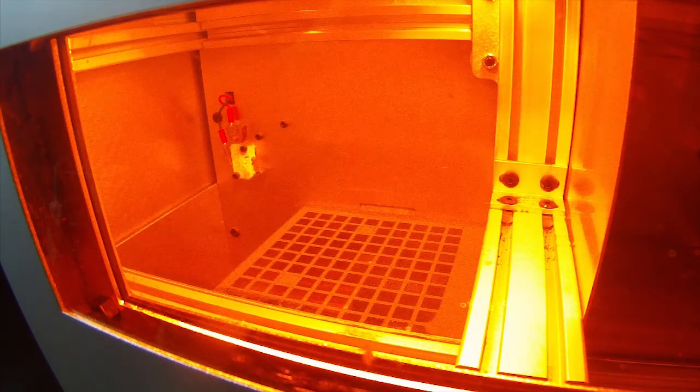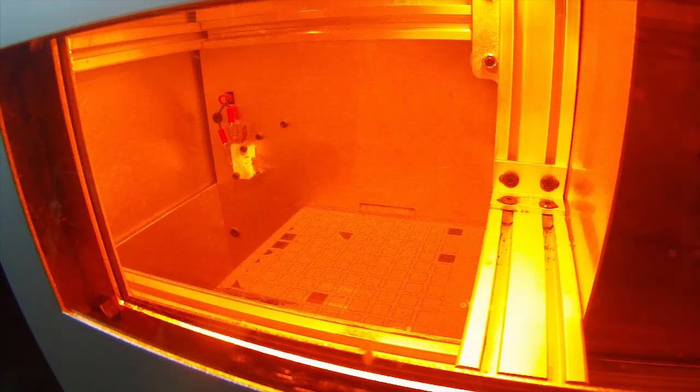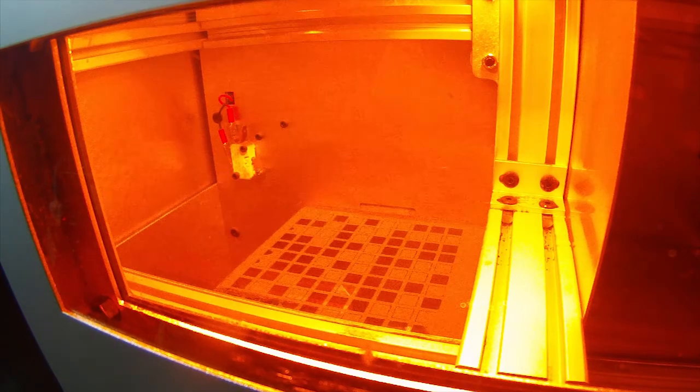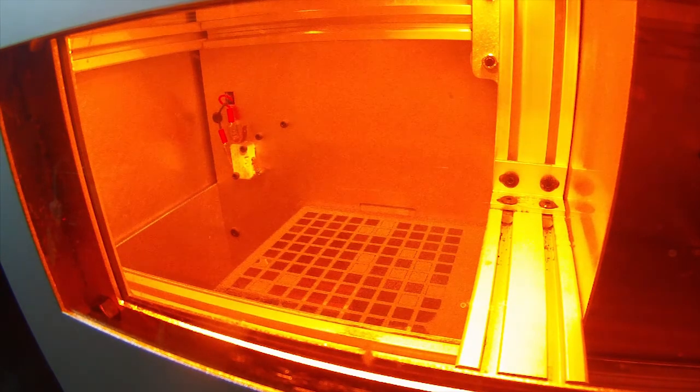However, eventually that still didn't really work. I still had a bit of curling on the right side, and then I lowered the laser speed to 525, which helped dramatically. There's more plowing right there.